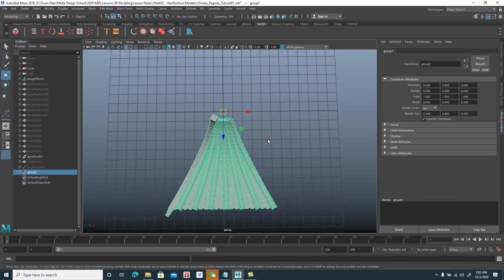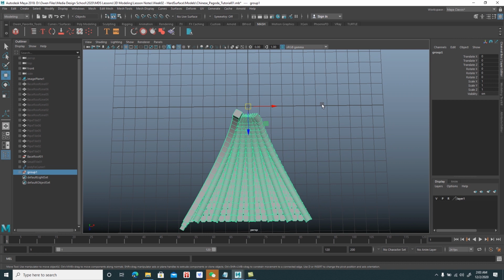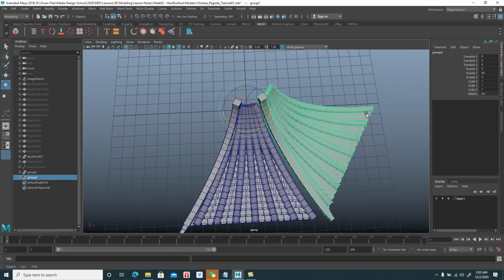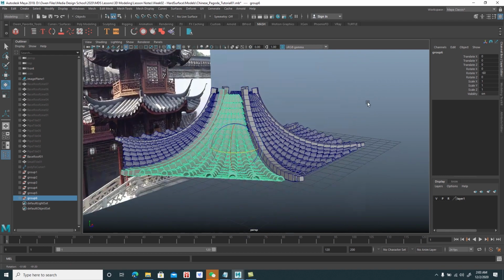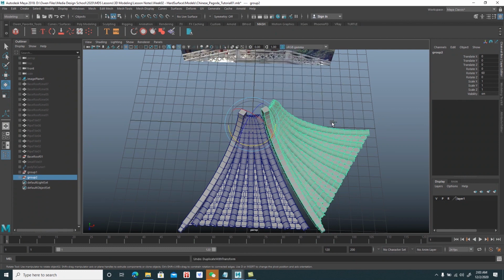So now if I go to my channel box and press Control D, press E for rotation, and press J for 15 degrees increment, I will get a 60 degrees rotation on the Y. So if you do this and you shift D, that's okay, but it will generate a copy of your group, which is not what we wanted.